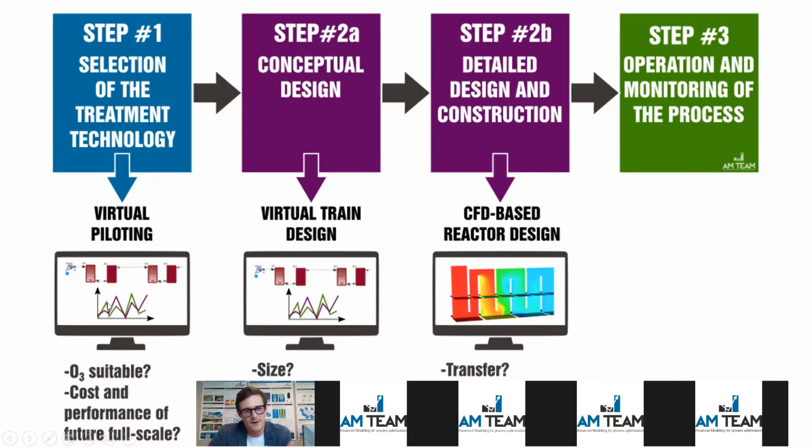Typically, we use a very similar approach there. We build this full-scale plant, or several full-scale candidate plants with different volumes. We test different ozone control strategies. Should we go for a delta UV, DOC proportional, flow proportional, maybe a hybrid of those? And you can run them through the model to have the conceptual design. So the questions there are the size and, of course, the performance of the installation and the cost.